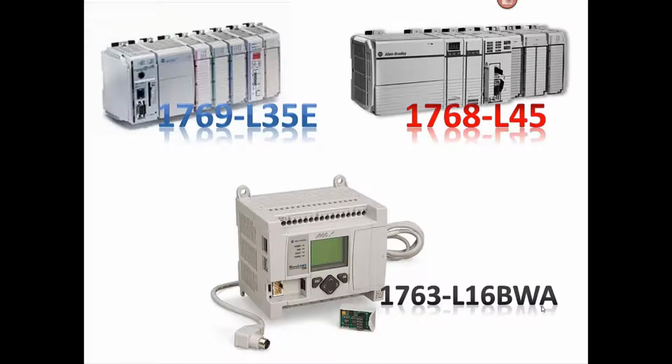This means of communication is time-consuming to implement, mainly because it requires access to your memory, your skill of recall when configuring the instructions to communicate, and requires knowledge and access to more locations in the program code. So the solution to controllers from the same manufacturer but not the same platform is usually message instructions and communications adapters, usually with some support.